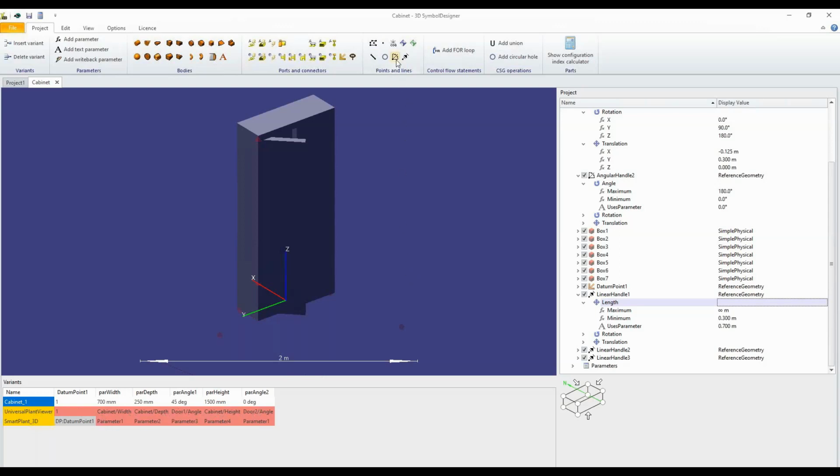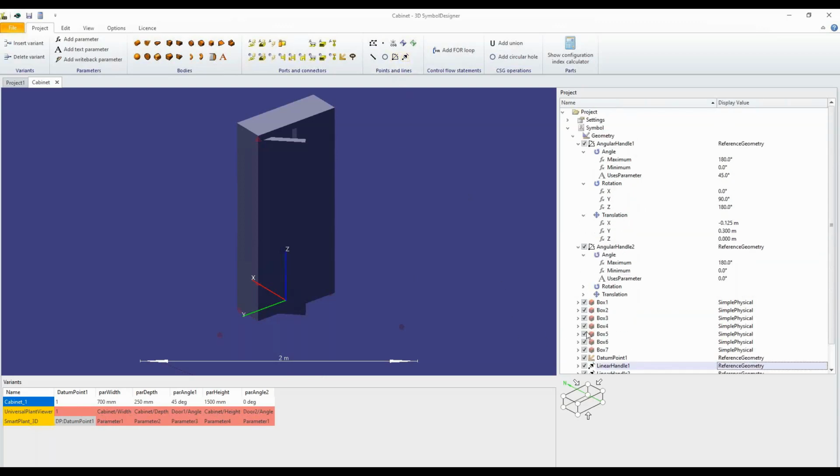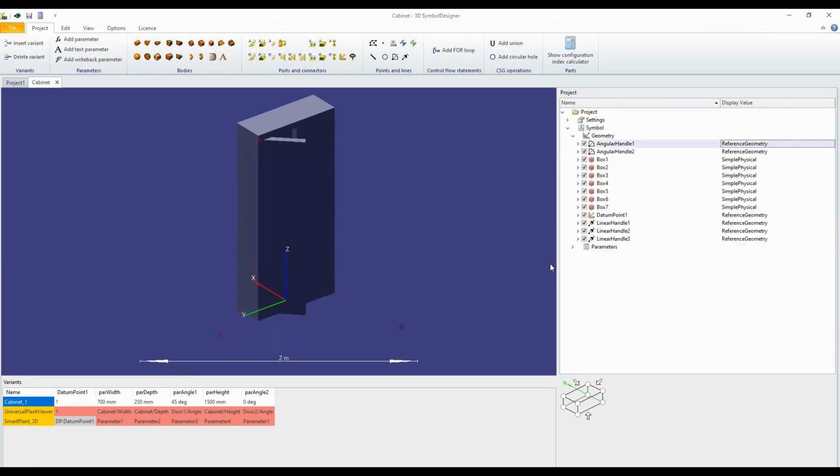And you can use, if you like, these buttons here to create the bubbles. They are not necessary, but for sketching, I think it's very useful to have them in here. And basically that's all. So you just save the symbol. So you have this Excel file, you place it in the folder, you create a little screenshot for the icon, and you place the name of the Excel file in the text file. And there you go. Then it's available in the catalog of UniversalPlantViewer.